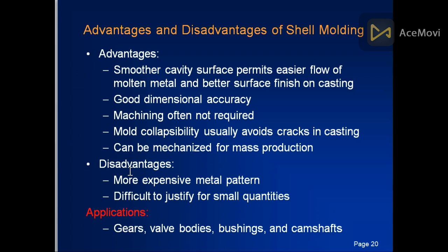But it also has some disadvantages. It is an expensive process because a metal pattern is required, and it is difficult to justify for small quantities. For small production, for example one or two parts, it is very expensive.